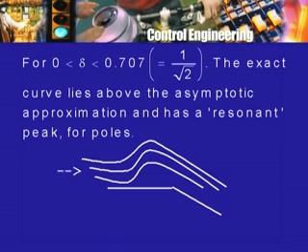At the very low frequency end, there is not a big error. At the high frequency end, the error is also not very big, but near the corner frequency, the error can be substantially large, and as delta decreases, in fact, this peaking goes on increasing. Now, this is something you should try out on your own. Of course, you can consult your textbook where the curves are given, but you have learnt enough calculus to be able to show this. That is, take s squared plus as plus b, replace s by j omega, and then take the modulus of that.